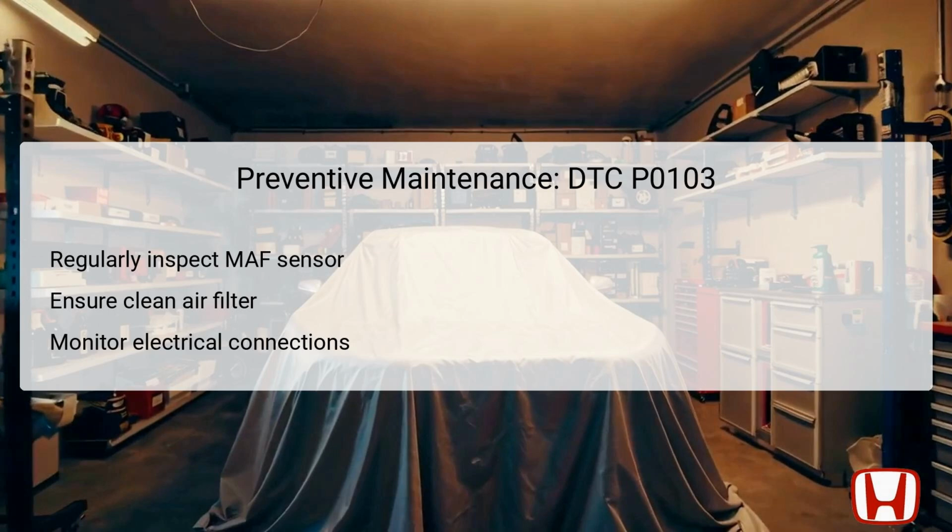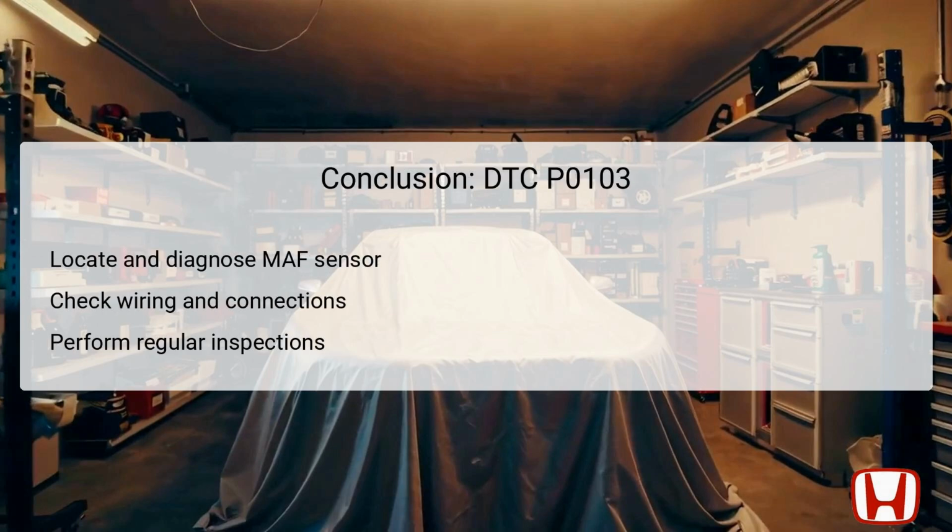In conclusion, diagnosing and addressing DTC P0103 involves a methodical approach focused on the MAF sensor and its associated circuits. Understanding the role of the MAF sensor and maintaining proper connections is vital for effective vehicle performance. Begin troubleshooting by assessing the sensor data, checking wiring connectivity, and performing necessary repairs as needed.